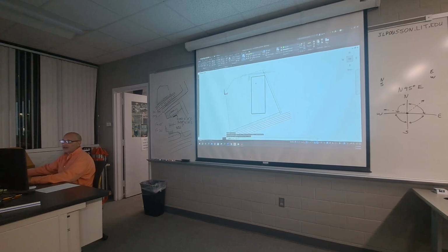I can select that object and then tell it this is my base point. When AutoCAD says specify rotation angle, I'm gonna select reference, one of the options down there. Then I'm gonna tell AutoCAD take this endpoint, which is gonna stay right there, and then take this endpoint and align it with that intersection, that endpoint, something like that. And AutoCAD will rotate it to match it.